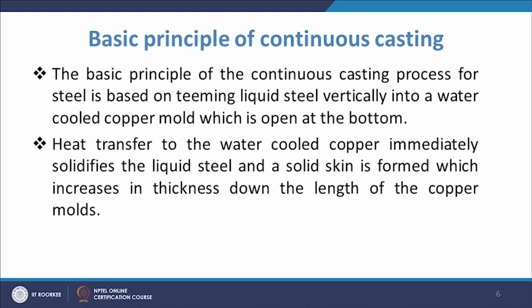Also, the mold is made of copper. So, heat transfer to the water cooled copper mold immediately solidifies the liquid steel, and a solid skin is formed which increases in thickness down the length of the copper mold.